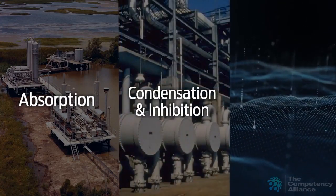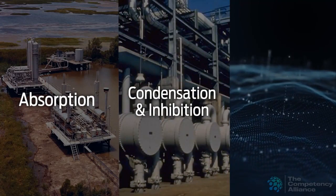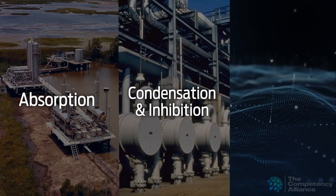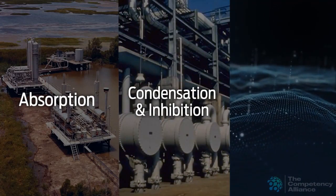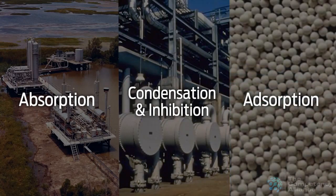Condensation and inhibition. Water is removed by condensing it, usually with refrigeration, and inhibiting hydrate formation with an inhibitor, usually glycol or methanol. Adsorption. Water is removed by adsorption onto a solid desiccant. Common desiccants include molecular sieve, which is a zeolite, silica gel, or activated alumina.